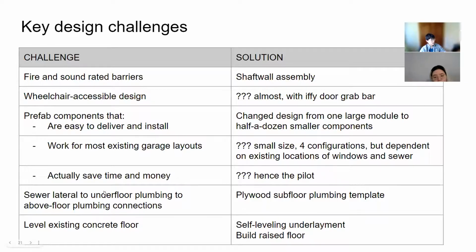All right, last 2 design challenges here for the sewer lateral to underfloor to above floor, and how to get all those connections to happen precisely and with the appropriate inspection clearances. We think some sequence around this plywood subfloor plumbing template allows you to do what you need and build an above floor and subfloor plumbing assembly offsite and bring those in at different stages in the sequence.